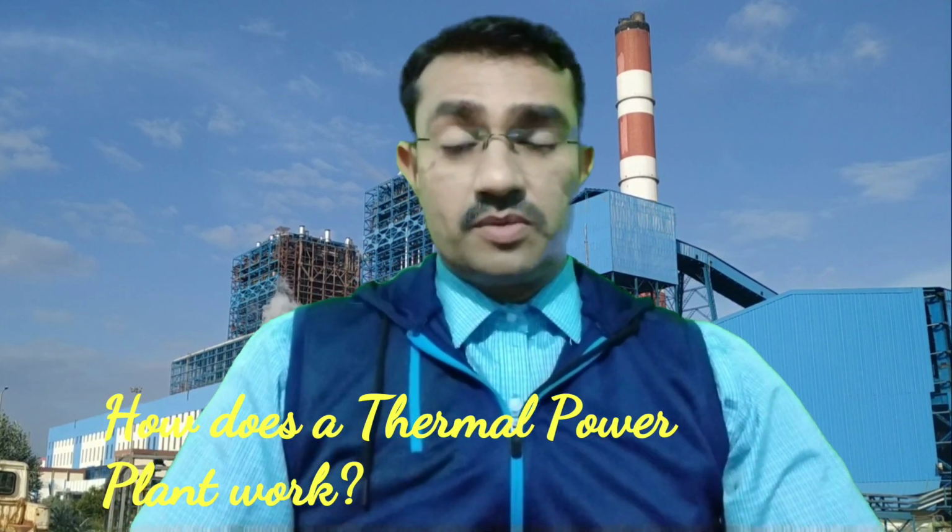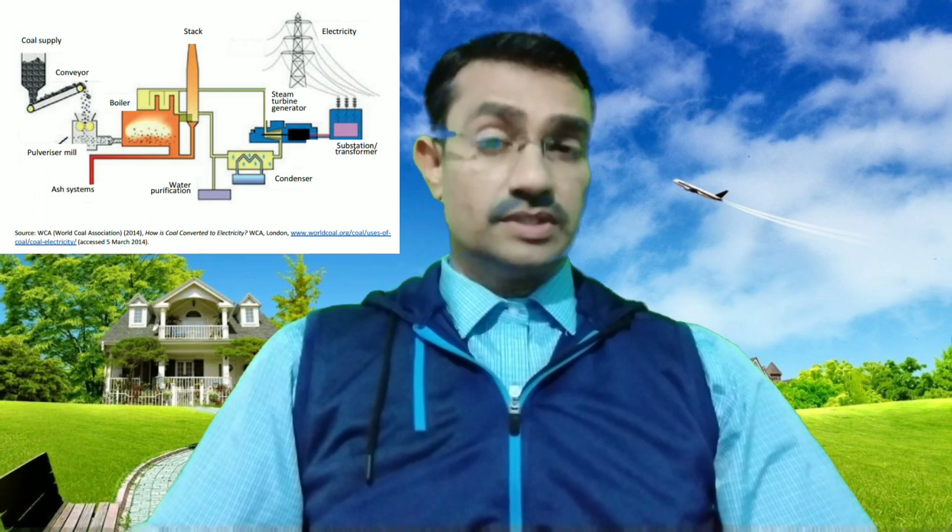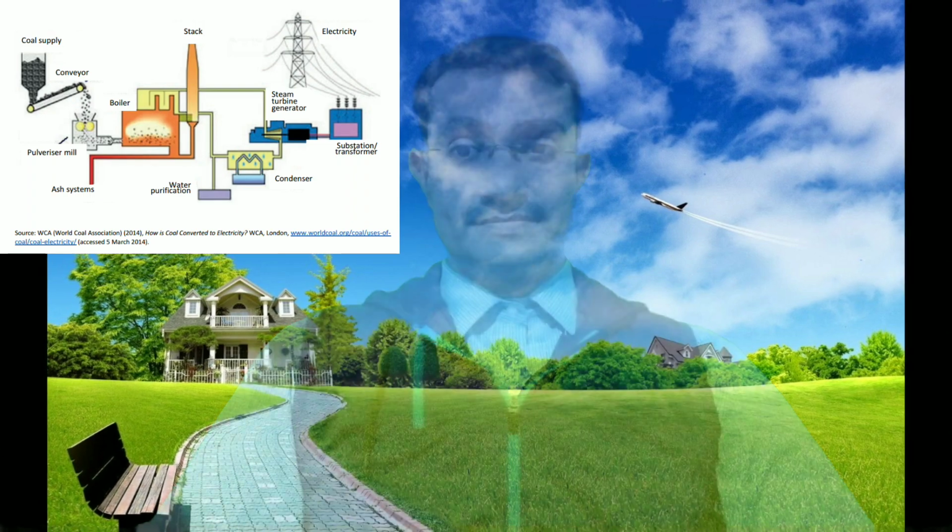Coal is transported from coal mines to the generating plant. The coal from storage is first crushed into small particles at the crusher house and then taken into a pulverizer to make it into powder form. Fine powder coal undergoes complete combustion, and thus pulverized coal improves the efficiency of the boiler. The ash produced after the combustion of coal is taken out of the boiler furnace and then properly disposed. Periodic removal of ash from the boiler furnace is necessary for proper combustion.